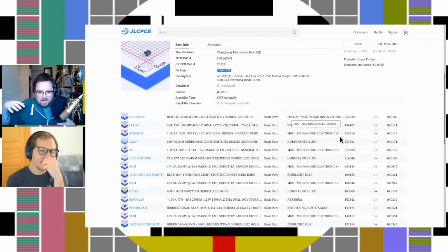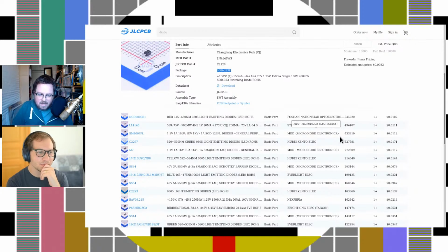So that's how I stumble my face through circuit designs that I don't understand. I figure out what I want, and I go and look at how other people do that, or what parts make that up. Like, I've got the row column switches, then I have to feed those GPIOs into somewhere, like a microcontroller. So I might look up "microcontroller key switch example" or something like that. And then I figure out, okay, they've got some resistors and diodes, and I understand why they have those resistors and diodes there. Now I need to go figure out which ones I'm going to use,